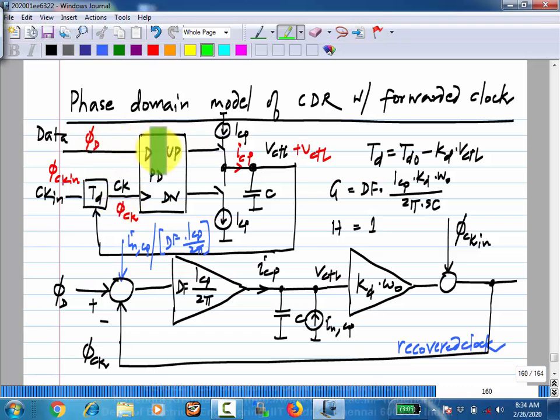this clock edge, the rising edge of the clock, is in the middle of the symbol period over there. So DC gain being 1 means that essentially if you apply a steady phase shift to the clock, that is, you move all the edges by some amount, all the clock edges also will eventually move by the same amount. So you can think of other cases like this, right?